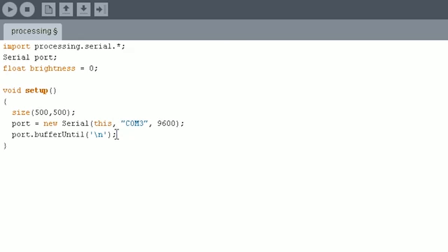So remember, we're doing println, which prints a carriage return after it sends you each value. Every value you get in the terminal is on a different line, if you remember. The thing that tells it to go to the next line is \n, which you can't see, but the computer's terminal program can. So we're going to know when we're getting a new value by looking for that \n.